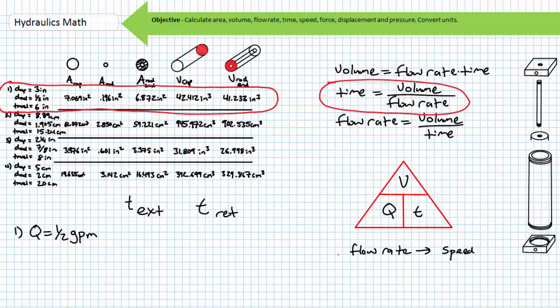Just think about this. No numbers. Which act is faster for a double acting cylinder for a constant flow rate? If you're on the right track, you said retraction should occur faster than extension. Faster retraction speed means it takes less time to do so because there's less volume to fill in comparison to the cap end without the volume of the rod removed. It makes sense. We haven't used any numbers.